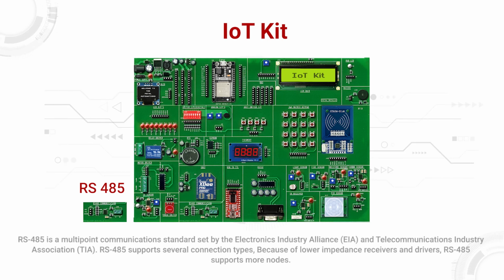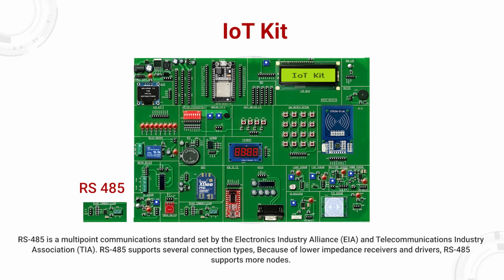RS-485 is a multi-point communication standard set by the Electronics Industry Alliance (EIA) and Telecommunications Industry Association (TIA). RS-485 supports several connection types. Because of lower impedance receivers and drivers, RS-485 supports more nodes.